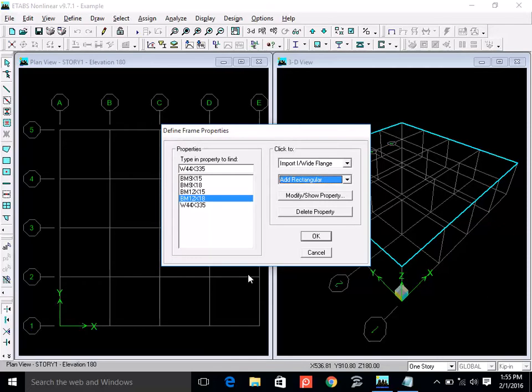Say 12 inch by 15 inches, 15 inch by 18 inches, or 18 inches by 21 inch, sometimes 15 inches by 21 inch. You know, there is no universal rule, but you will learn this when you practically design structures. The way you learn it, when you go to the design office as a fresh structural engineer, you study their previous designs. Their drawing sets are available from the previous projects.